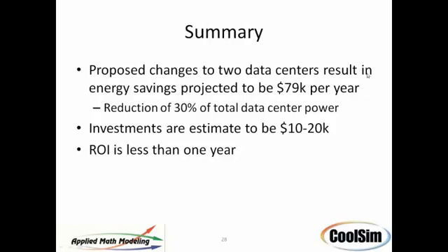Well understood. The fan manufacturers all provide fan curves, and you can tell when you get into a situation like that based on the downstream pressure. But even in that case, the downstream pressure is not constant. It varies across the room, across the underfloor. And each fan is different. For example, EC fans are different than the traditional scroll fans. So it's difficult to generalize, I guess, Jan. It is case dependent.